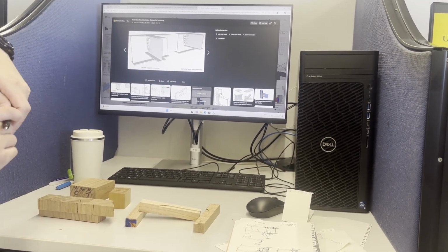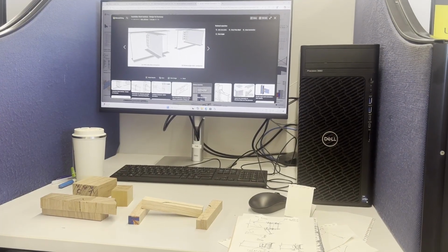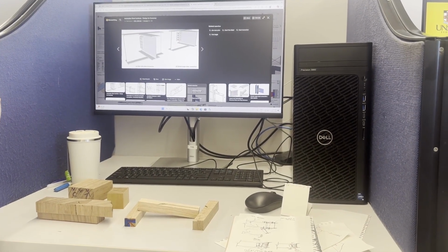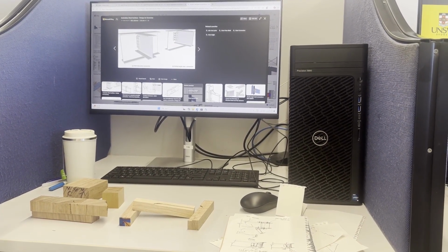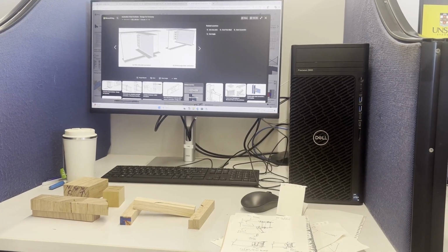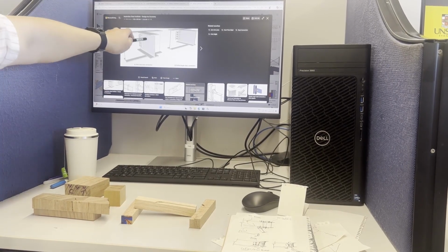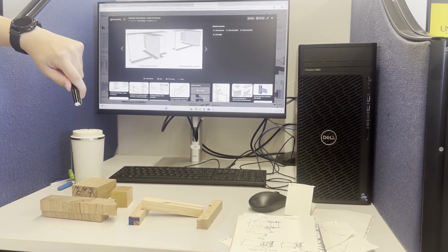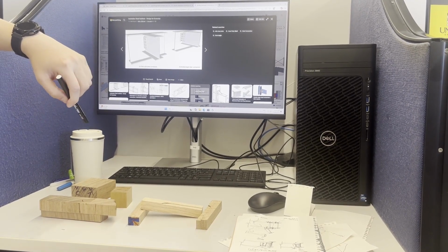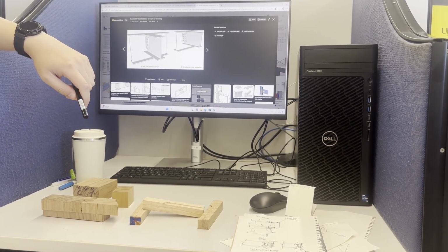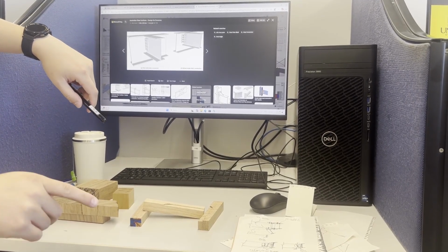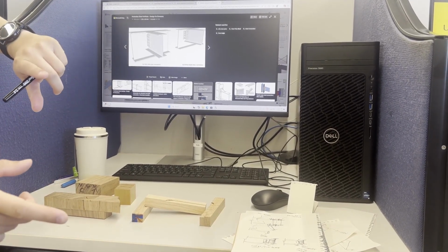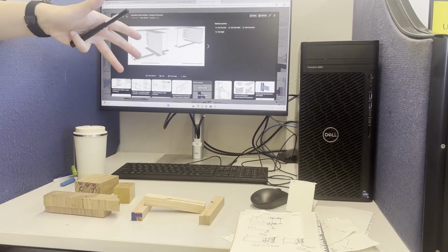Okay. For that example, would you need to take off the top flange and keep the bottom one as a whole piece? Yeah, that's more optimal if it's uneven beam sizes. Yeah. And because of that, would primary beams always be less deep than the secondary ones? Not necessarily. Primary and secondary are more to do with what relies on what. It depends on the beam lengths and stuff like that.